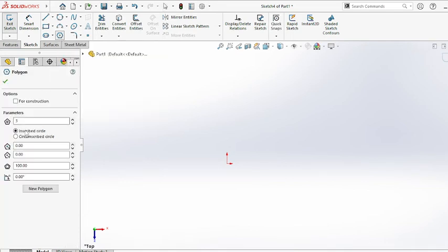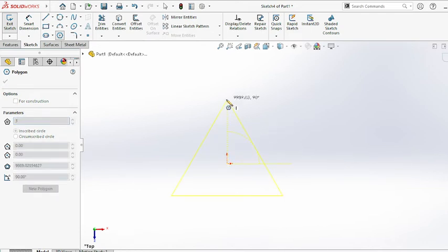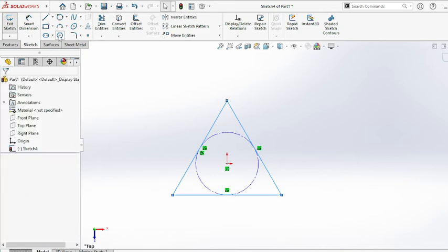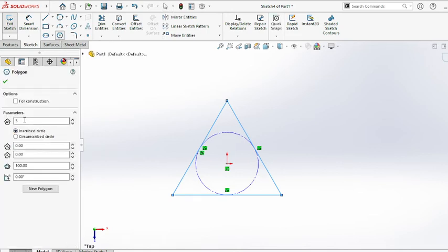Okay, see, you can click on the polygon. See here, how many sides do you need? For example, three sides, three, enter. You know inscribed circle, circumscribed circle. See, this is my start point, this is my end point. I want to draw a triangle; three sides means triangle only. For example, four sides: click on polygon again, four sides, I need four, enter.